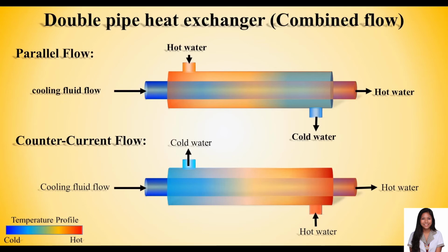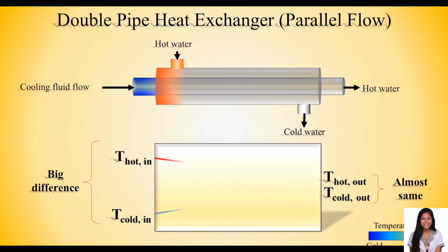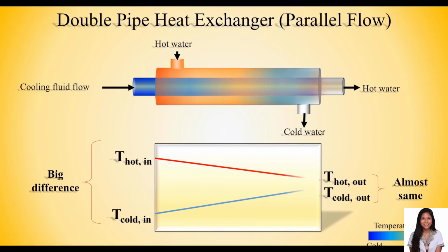topic. Again, to recap, in the case of a double pipe heat exchanger, of steam getting condensed on one side and water getting heated on the other side, the temperature of steam at condensation is 100 degrees Celsius, so the log mean temperature difference does not change, and hence the heat transfer in both counter and co-current, or also known as parallel flow heat exchanger, is the same.